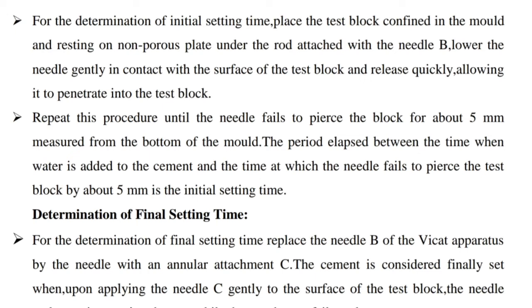The period elapsed between the time when water is added to the cement and the time at which the needle fails to pierce the test block by about 5 mm is the initial setting time. Determination of final setting time.